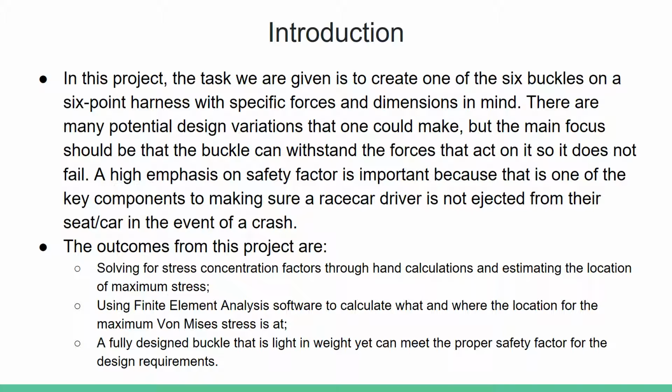The outcomes for this project are solving for stress concentration factors through hand calculations and estimating the location of maximum stress, using FEA software to calculate what and where the location for the maximum von Mises stresses are, and a fully designed buckle that is light in weight yet can meet the proper safety factor for the design requirements.